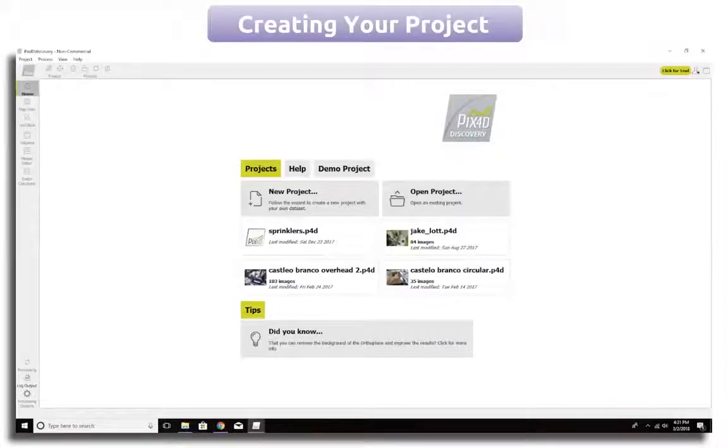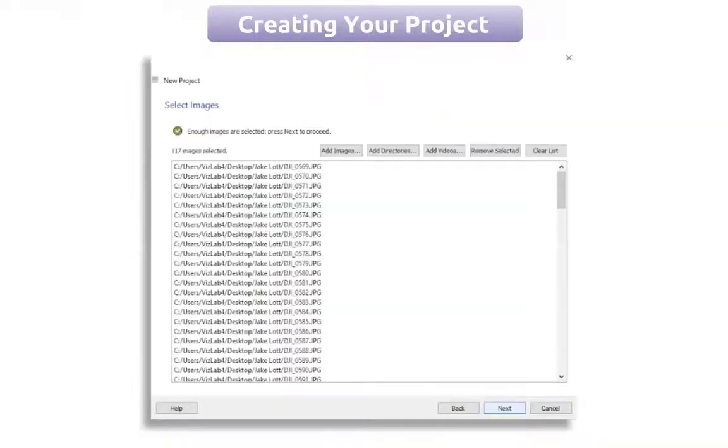And then once your images are ready, you'll simply launch the Pix4D app and create a new project, right? And this is where we get into some of the settings you need to make sure that we're doing things correctly so that we get the correct outputs that we want. The first thing that you're going to need is to select the location of your images. From a file organization structure, I'd really recommend keeping your images organized by project and then by flight, so that if anything goes wrong with images from one flight, it's really easy to figure out which flight that was, and so if you need to go refly something or something like that.